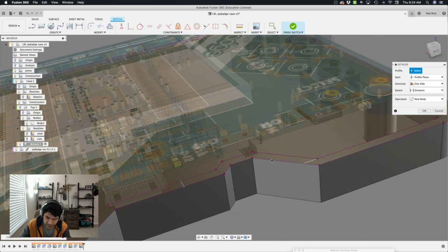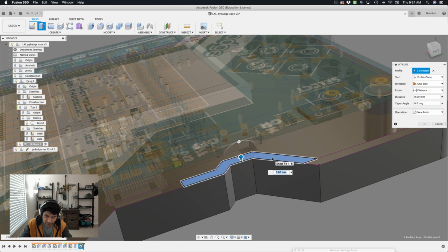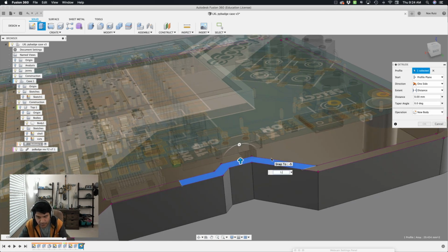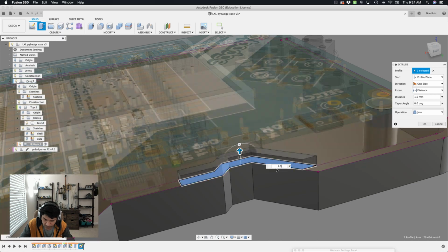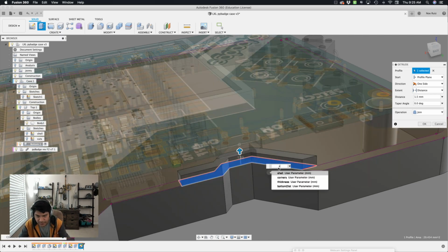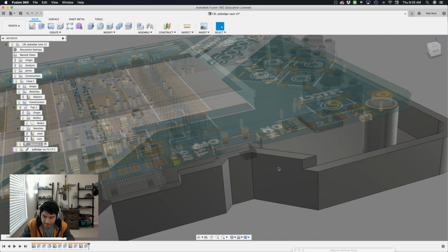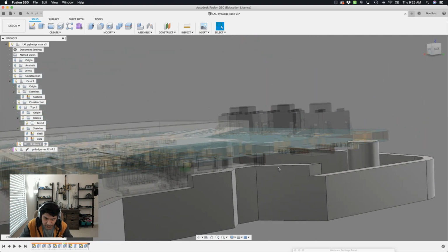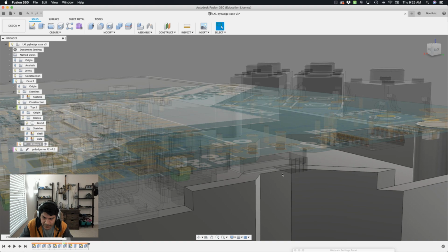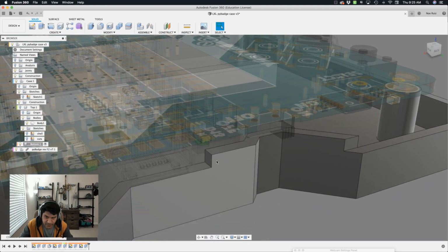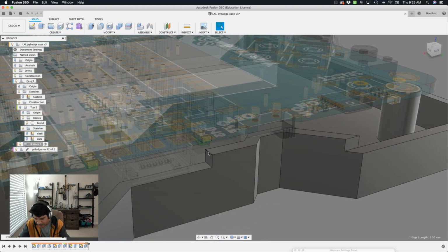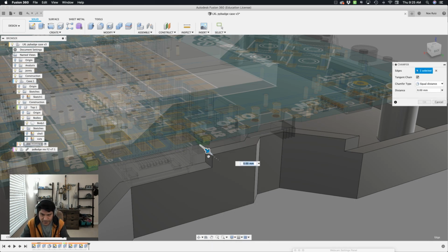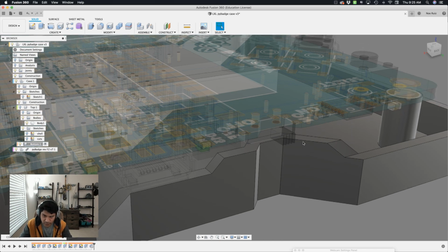This little section here that we just kind of chiseled out, we can extrude and give it that 1.5. Since it's 1.5, we could also put just shell because that is the same value, and hit OK. That looks cool. Another thing I want to do to it, let's take a look at it. Yeah, you've got just enough clearance to keep that down in there. I want to create some chamfered edges to really go with that. So that's a chamfer, right? Yeah, so that's the shell. We'll also do one over here. Look at that. That gives us those really nice chamfered edges.